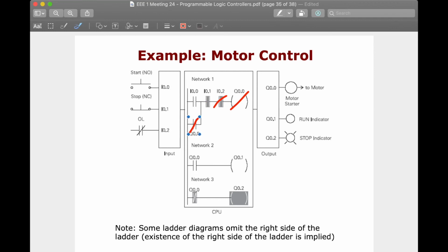and so the motor will turn off, and so this will also be unenergized. At the same time, if the overload protection detects that, say for example, the current that's flowing through the motor is overloaded, so the overload protection will be energized, and that means when the overload protection is energized, it becomes open because it's normally closed, and when it becomes open, the coil is now disconnected, so it again turns off and this turns off, right?